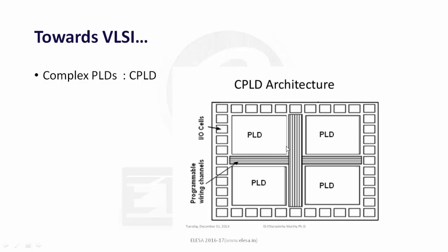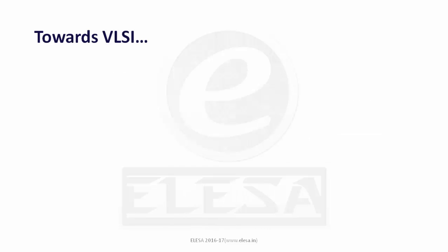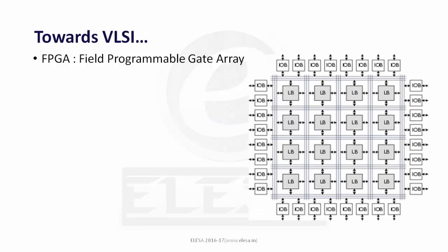Right, so these are the programmable interconnections. These are used to interconnect these PLDs. So overall the functionality of a CPLD is much larger than a single PLA and PAL structure. That's why CPLD is actually used. And the matter of interest is the FPGA.